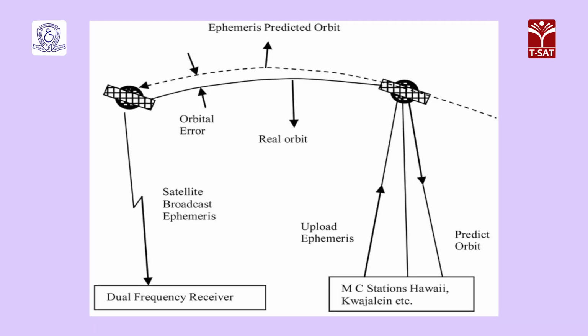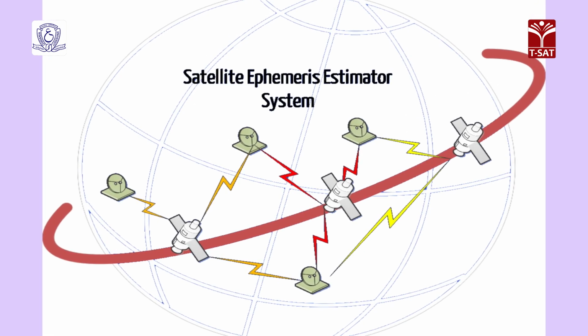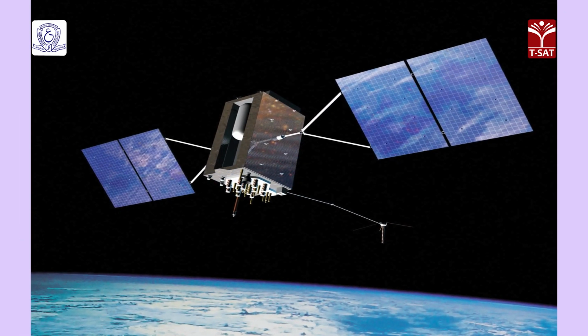Ephemeris error. Estimates of ephemeris for all satellites are computed and uplinked to the satellites with other navigation data message parameters for rebroadcasting to users. As in the case of satellite clock correction, these corrections are generated using a curve fit to the control segment's best prediction of each satellite position at time of upload.